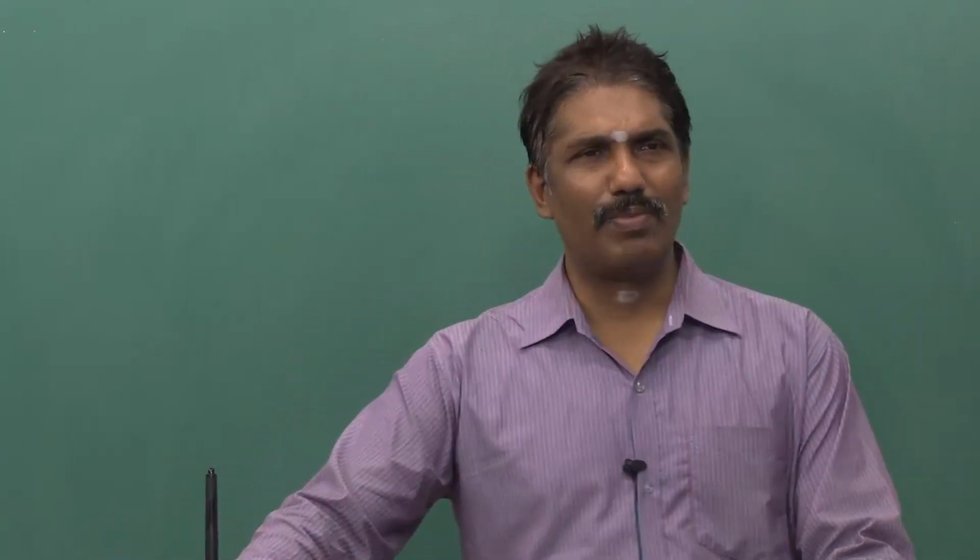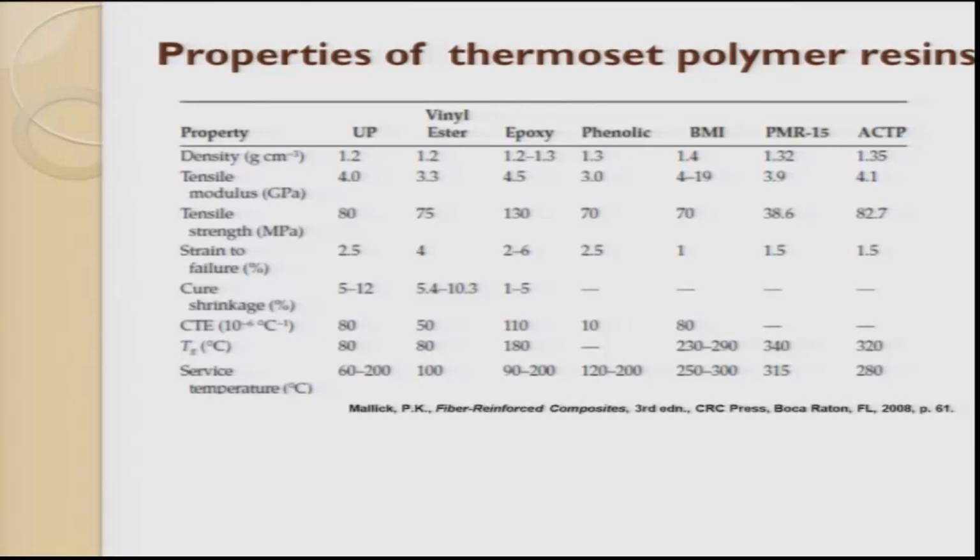Generally, polymer composites over a period of time get degradation in their strength. This happens because of environmental conditions like hygroscopic effects and a small amount of polymer degradation. That's why service temperature is also very important, and on top of it UV exposure plays a very important role in deterioration.